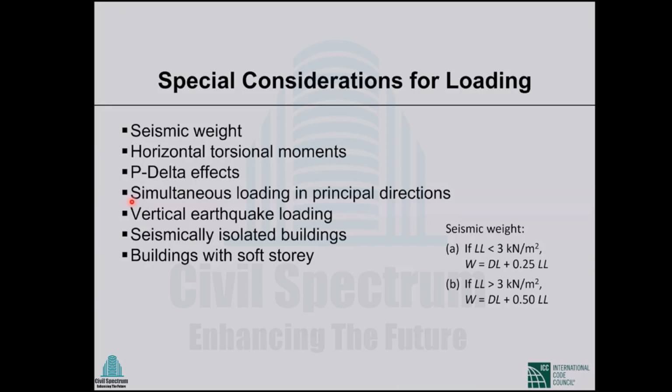In some cases we don't have to, but the way we design our buildings in Bangladesh, in most of the cases, a single vertical member takes loads from or resists loads in both the directions. That's why these simultaneous applications of loading will be required. So this is something new that you have to understand.